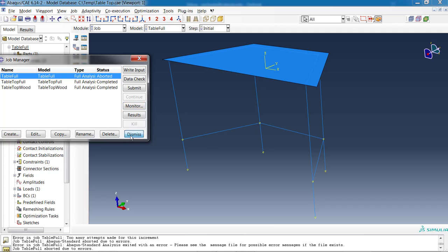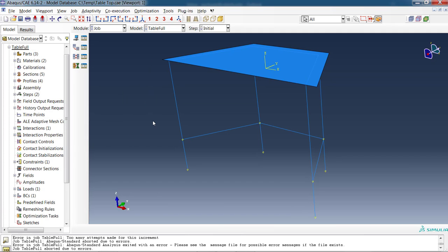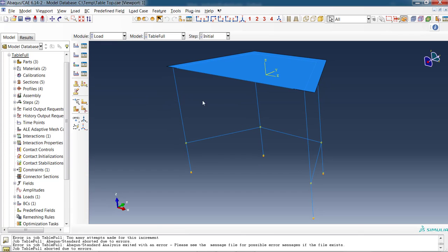The next set of troubleshooting is basically to avoid flying blind. I've attempted to submit this job and it didn't run. I don't know what the problem is yet. I can guess and change things, and that is certainly an approach a lot of people use. But my suggestion is to go back to your model and change how you defined it so that everything is tied down somehow, connected in some way.